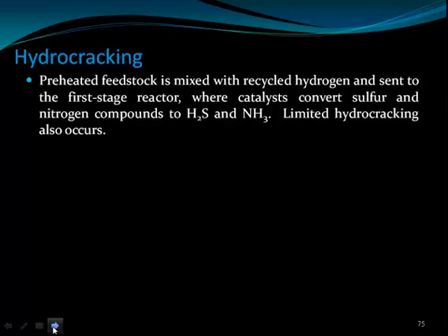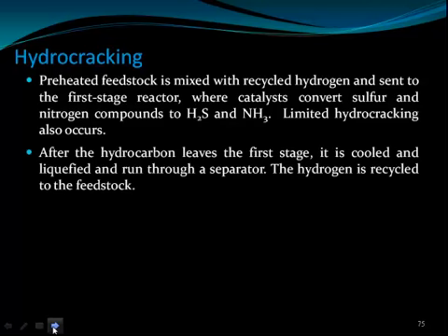Then the preheated feedstock is mixed with recycled hydrogen and sent to the first stage reactor, where a catalyst converts sulfur and nitrogen compounds to hydrogen sulfide and ammonia. Limited hydrocracking also occurs in this one.